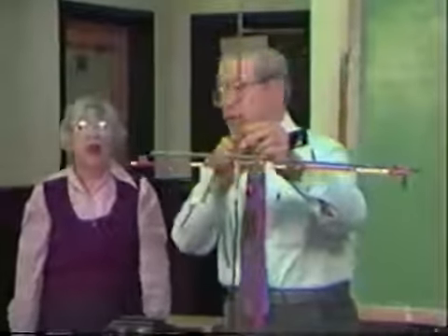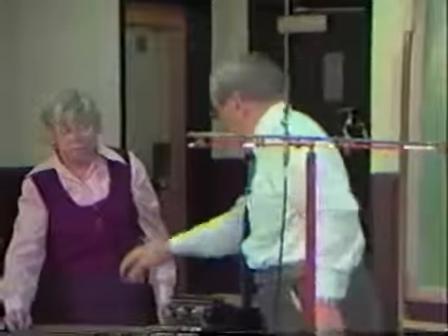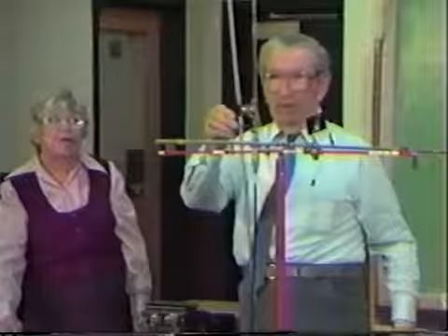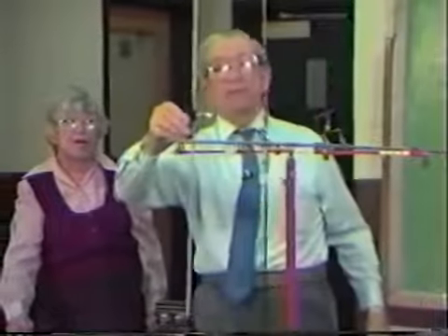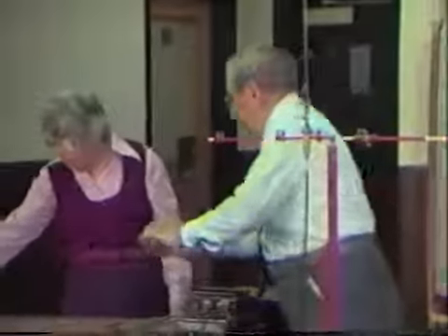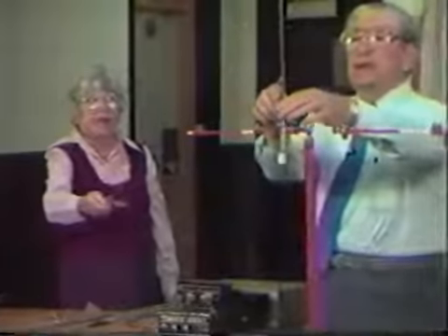Oh, try it, man. No, it may be lit. Try it again. The light is not lighting. Let's see if it's getting any radiation at all. Try it. Yes, there is some radiation from it. Now, this is very interesting. That bulb is not lighting. I'm going to do something here to demonstrate the difference in the quarter wave antenna when it looks at ground plane. The four radials, the four little wire radials. Try that again, dear. Nothing. All right.